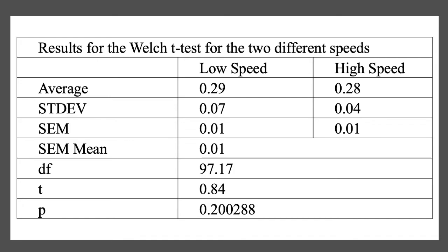Next, an unpaired t-test was carried out on all the data for low speed and for high speed. The confidence interval was found to be 20%, which suggests that the chance that the difference between low and high speed is actually zero but has a value of 0.011 by accident is about 20%, which is not a very small value. Therefore, it can be said that it is quite likely that low speed has higher coefficient of drag than high speed, but not by much.